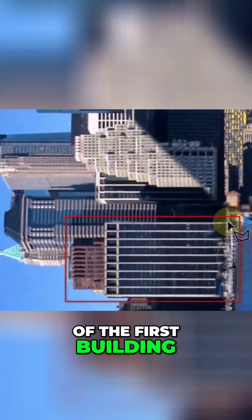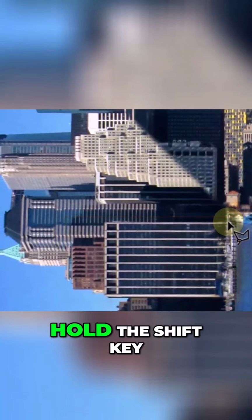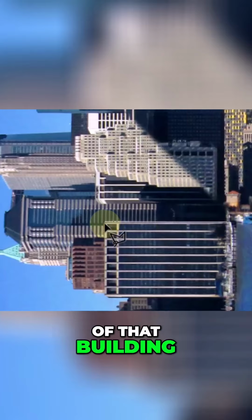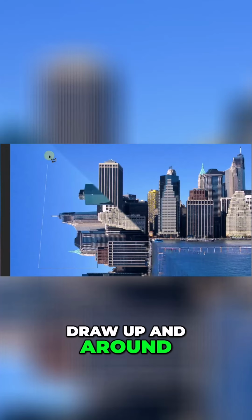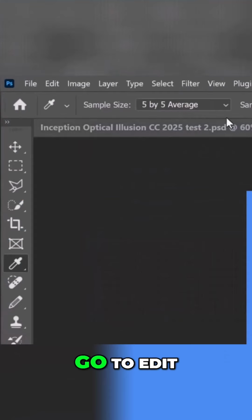Click and place it on the bottom corner of the first building that you'd like to see on the rotated skyline. Click and press and hold the Shift key as you drag the tool across the edge of that building. If you want to draw an angle, release the Shift key before you drag the tool. Draw up and around and place the tool on the top left corner of the first building you want to see on this skyline. Go to Edit